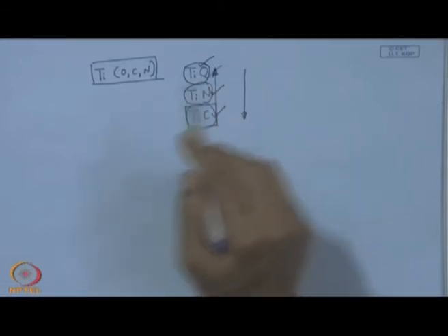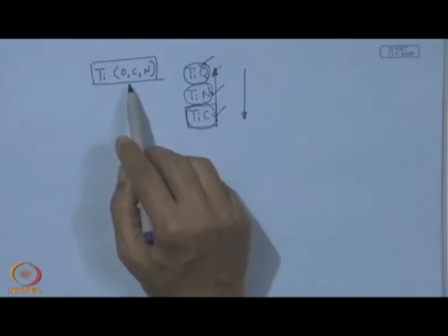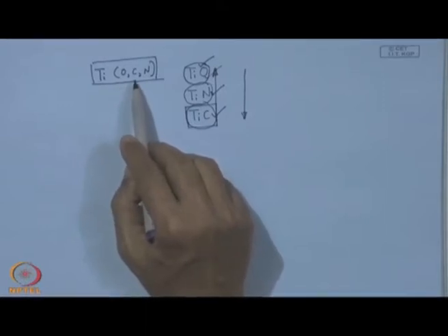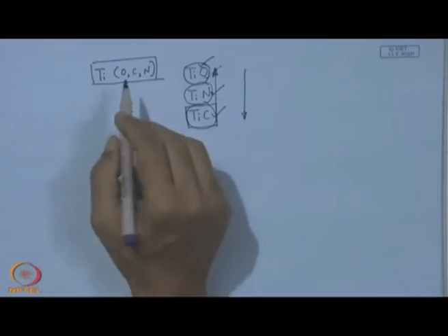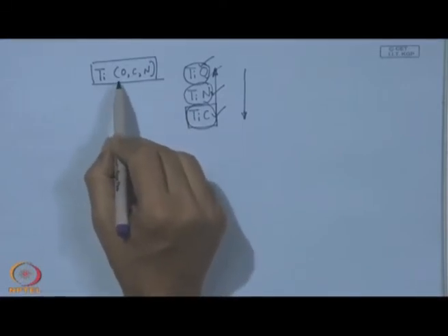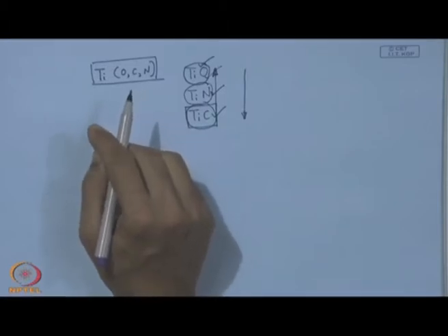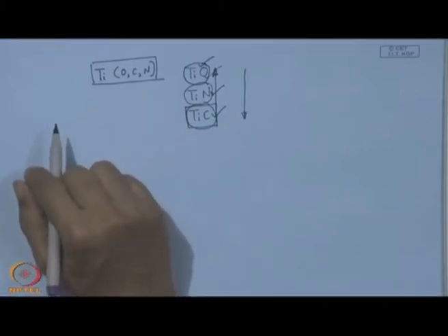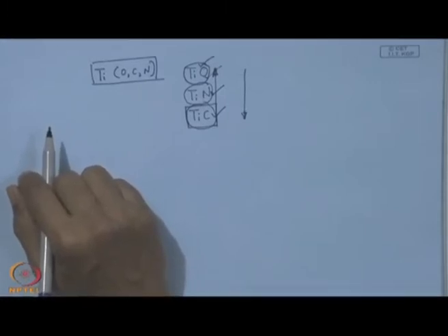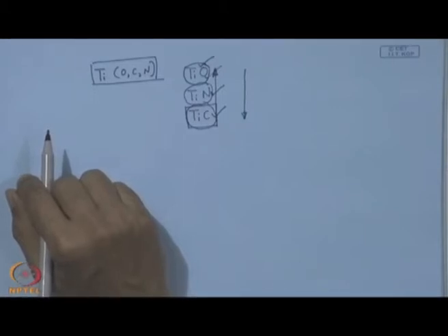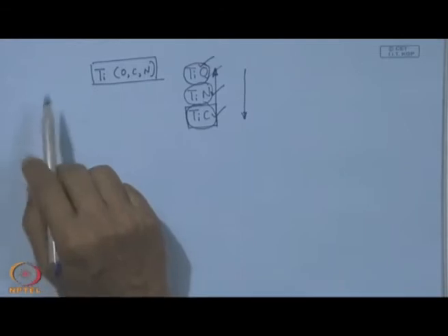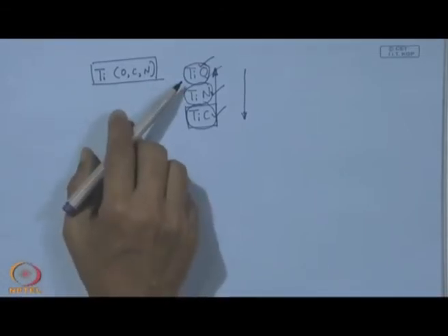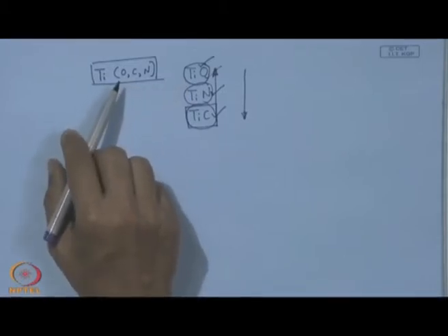Now, following the same logic which was behind this coupling of carbon and nitrogen, one can keep on mixing also oxygen with carbon and nitrogen, giving a new phase which is called titanium oxycarbonitride, and it has been found to be one of the effective coatings, particularly in those situations where temperature can be quite high, promoting or inviting diffusion wear or chemical reaction type wear, and in that case it has been found that TiO is playing a decisive role in combating the wear.